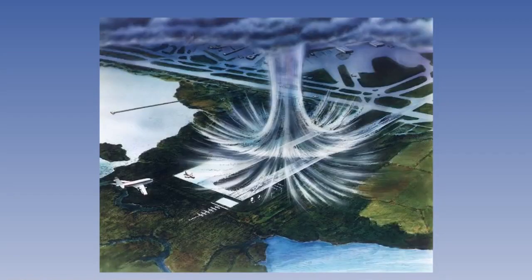By far the most dangerous form of wind shear is that which is generated by cumulonimbus clouds, often known as Q-nimbs, and their associated weather of heavy rain and hail, which can give rise to the phenomena known as microburst, and its bigger brother, macroburst.